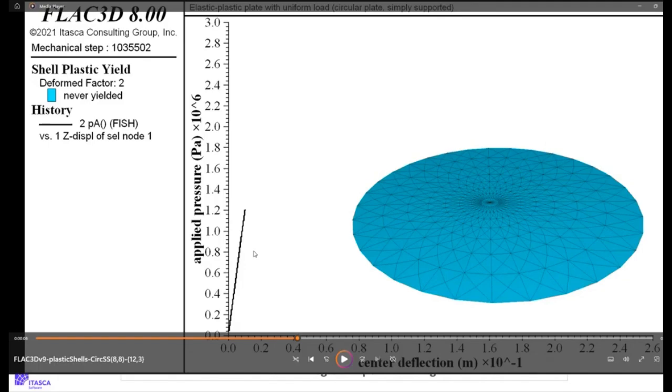And once something starts sliding, that means it's no longer elastic. That means if you unload it, it won't go back to where it was before, because energy is dissipated when it slides. In this type of world, we do that in a continuum way, where we have a whole theory called plasticity that lets things basically start to fail.